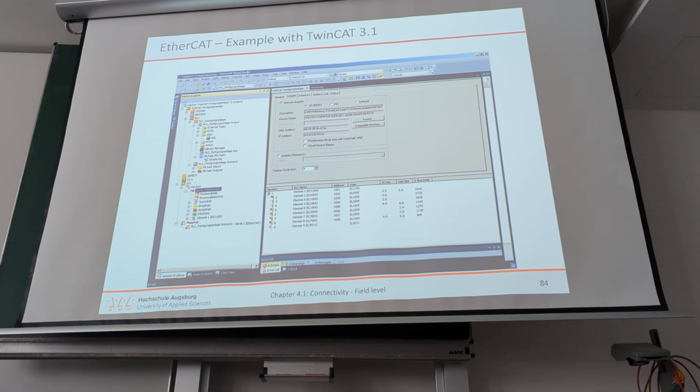And then, if you have 1 million steps, that would be 1 micron per step, and then you already have missed 31 steps, so your control cycle is up the next time. So it's really time critical if you want to have high performance milling processes to get a fast cycle time.